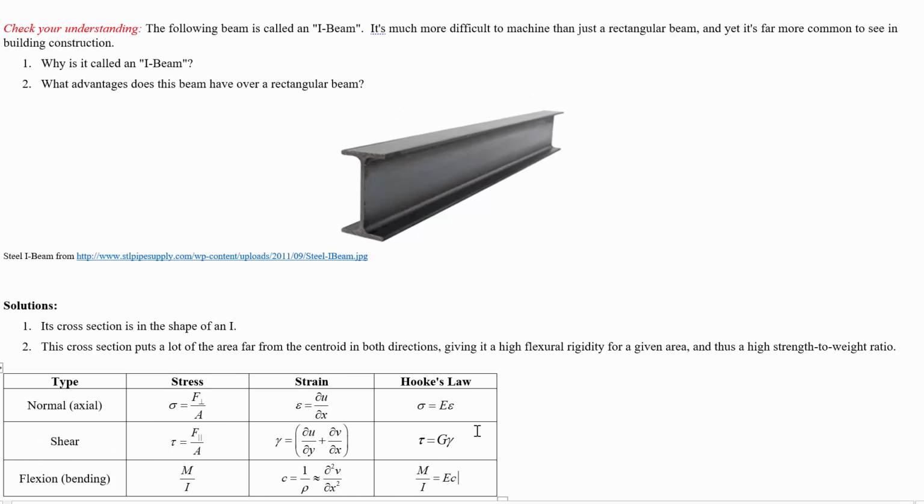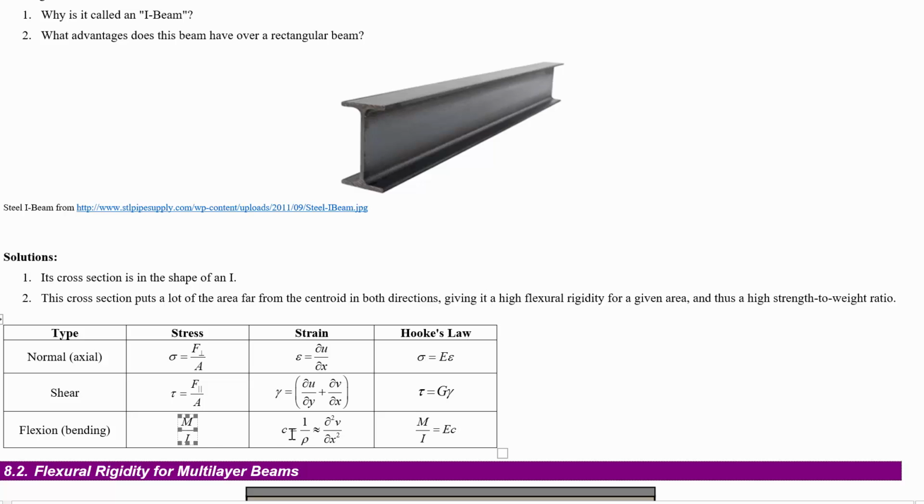And the Hooke's law that relates this stress to this strain is actually just that this thing is related to the curvature through the stiffness, the same one as for axial stress and strain. And that's because bending is the result of lots of contributions of just axial stiffness of this material in response to stresses on the local level.